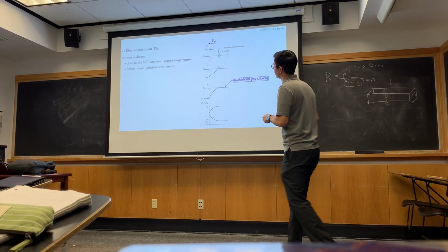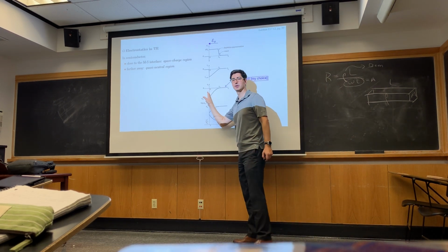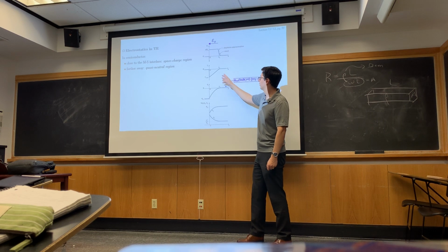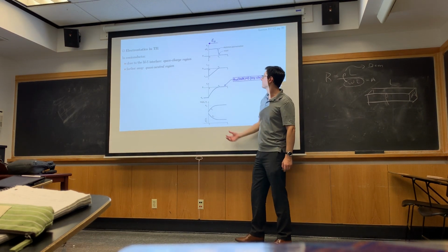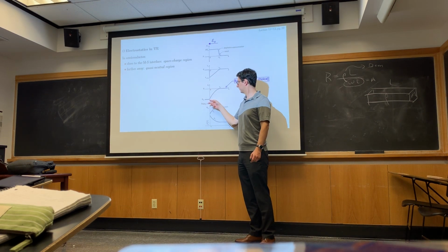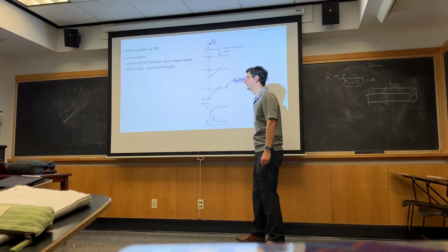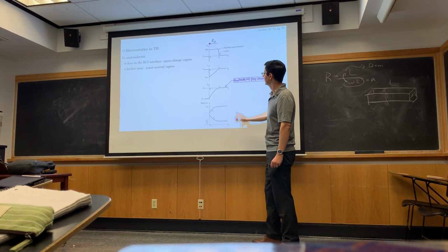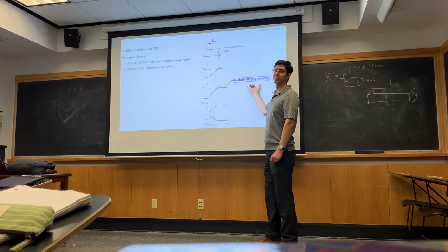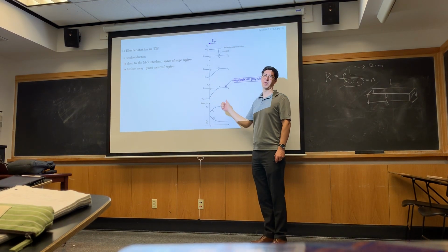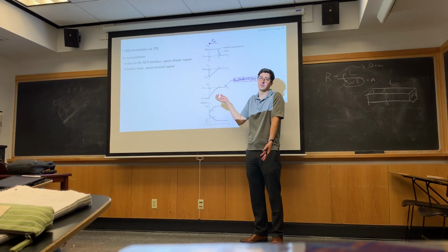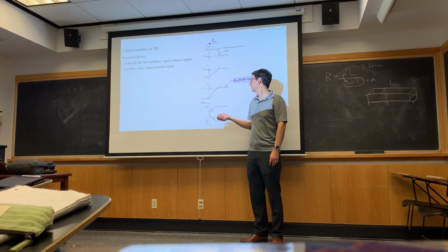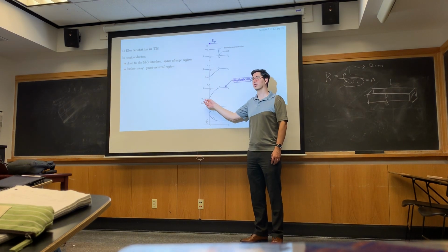Okay, and then we're going to integrate the electric field to get the potential. Integrating a straight line is going to give me a parabola. And then the electric field goes to 0, so then it's just flat here. I know that with potential, I can always choose my reference. Here, since I'm integrating from the right to the left, I just choose my reference as 0. And it has to go to phi bi, right?